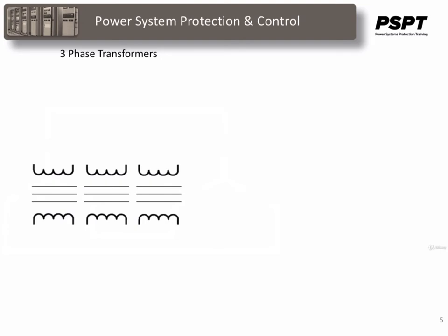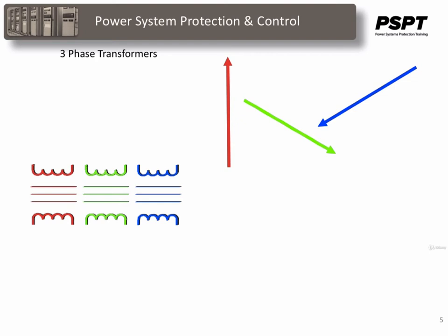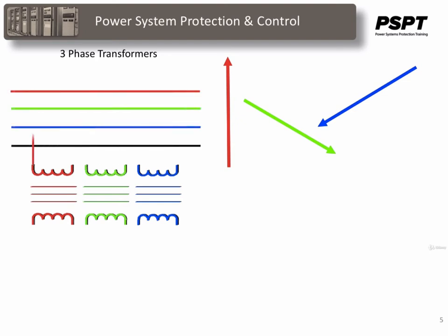When looking at three-phase transformers from a pure electrical perspective, they may be considered as three single-phase units consisting of a primary winding linked magnetically to a secondary winding. They become a three-phase unit by virtue of their excitation voltage and how they are connected to one another. They may also share the same core, but they may be considered electrically, at least, individually.